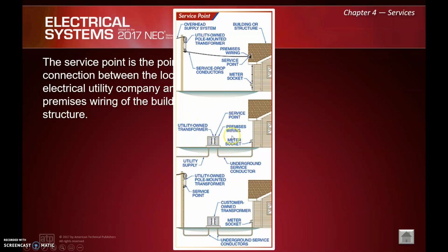Down on the underground, you're going to see the service point can kind of change depending on the situation, but it could be at the utility transformer. It could actually be at the utility meter, depending. In this case, it's actually at, in their instance, the pole-mounted transformer. That's not quite as common as far as what we see, but usually they're going to be at the transformer, or I think in most cases at the meter itself in our area.